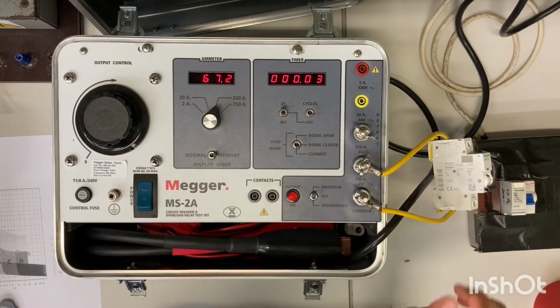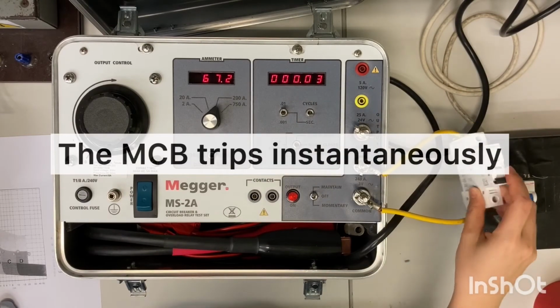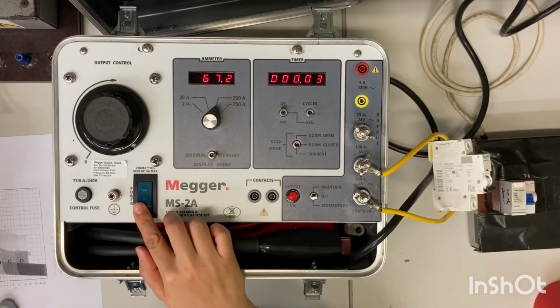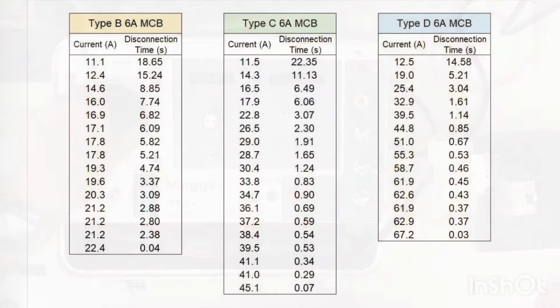The MCB has just tripped instantaneously. So this is the last set of data for the Type D MCB. These three tables summarize all the measurement data for the Type B, Type C, and Type D MCB. You may plot these data onto the graph to see if they comply with the British standard.